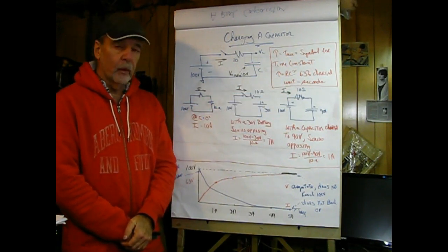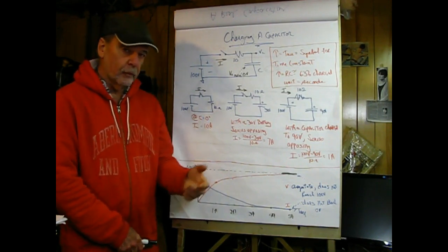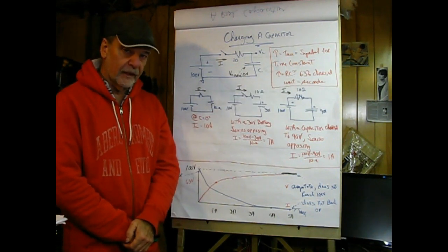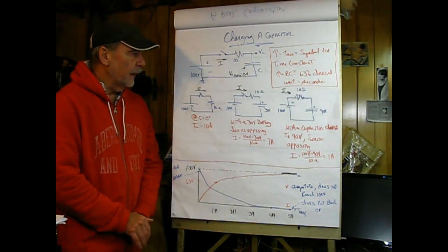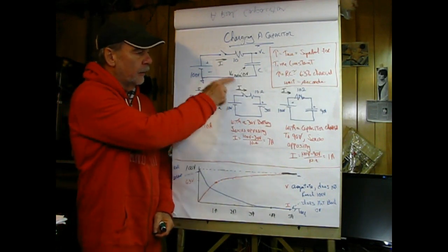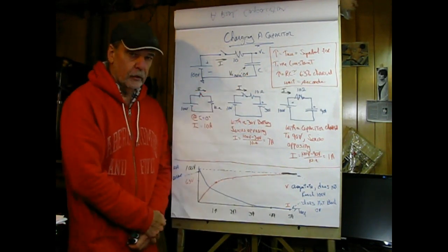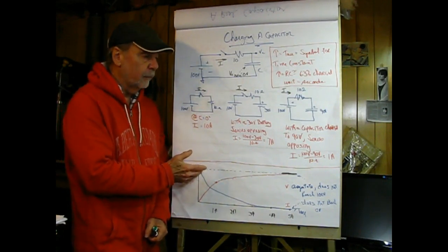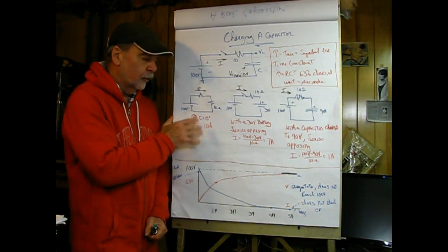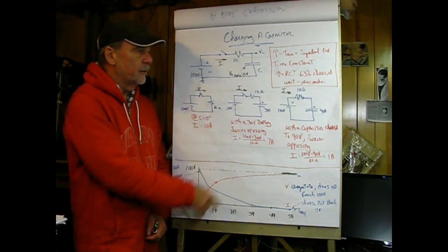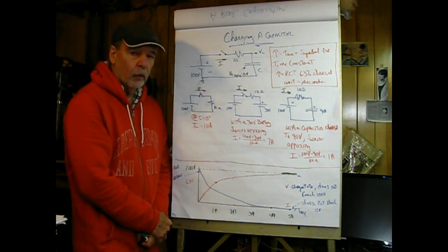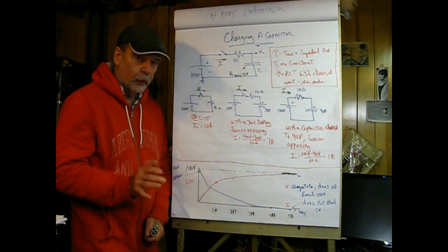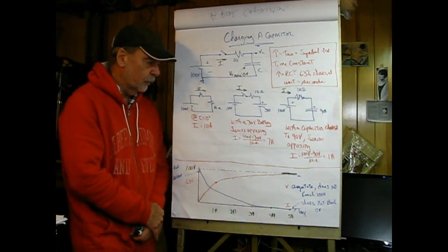As it turns out, one time constant will be where the capacitor is approximately 63% charged. And the unit for a time constant is a second. So let's begin by starting here, and it's important to note that VC initial, where we're starting out, in all cases that we're going to be talking about today is 0 volts. There's another step that would be required if it were, say, charged to 20 volts initially, or perhaps negative 50 volts, but we're not going to be worrying about that case.